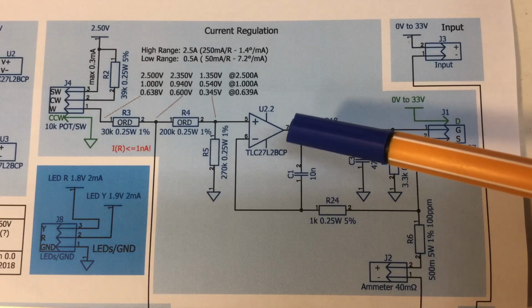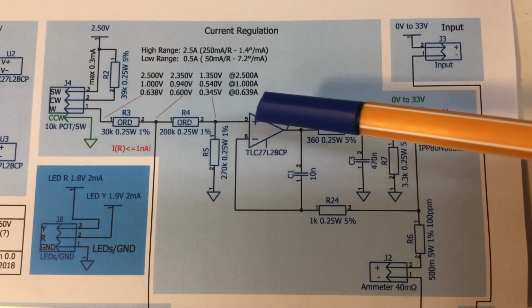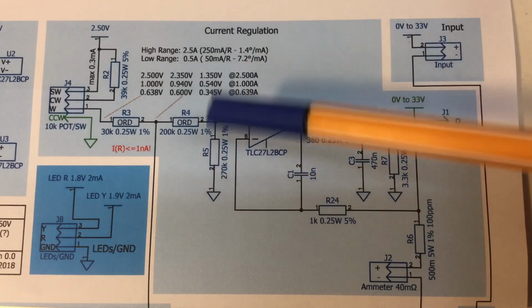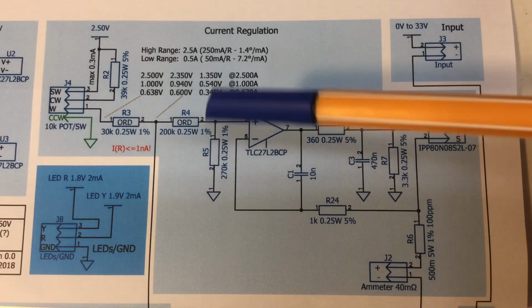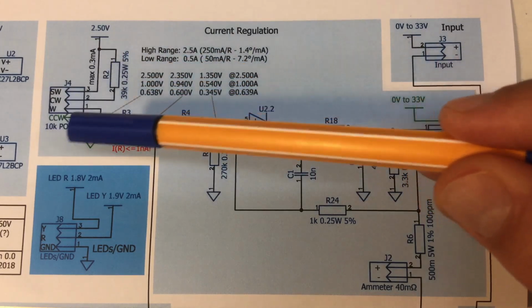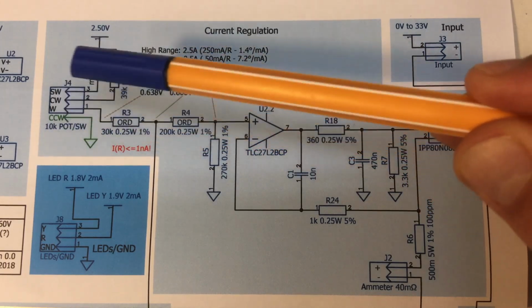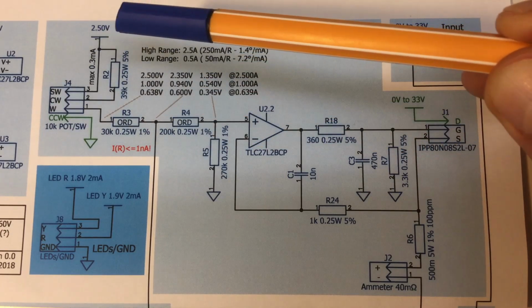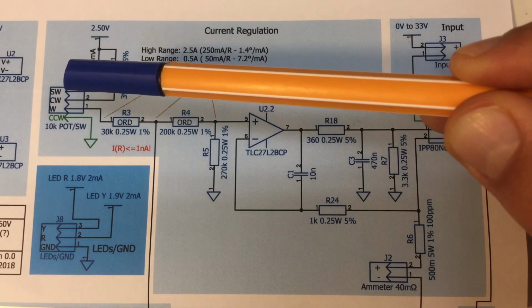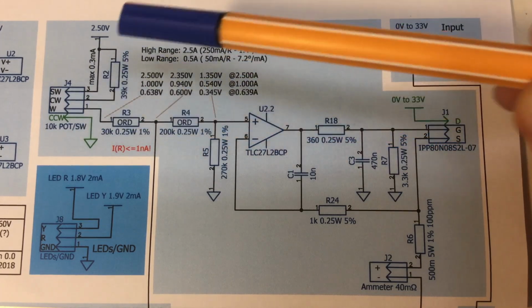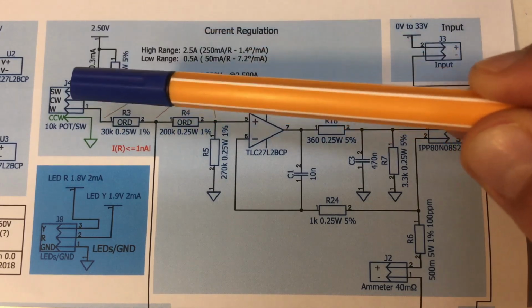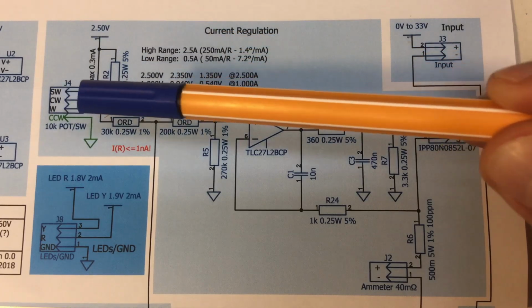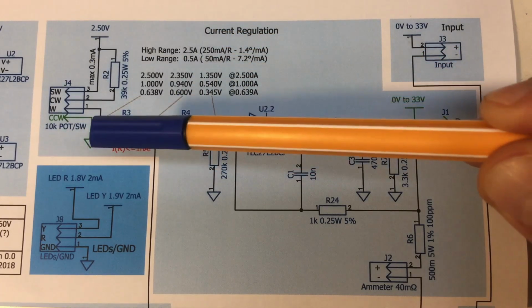So what we can do about that is avoid giving it hard kicks. And the very hard kick with a lot of spike and really dirty stuff comes, of course, if I actuate the switch here, which either gives the 2.5 stabilized directly to the clockwise connection of the potentiometer, or via that resistor, giving us the lower current range.